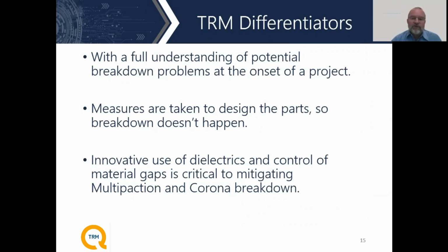We do things like overlapping dielectrics, eliminating gaps, other void filling things that we do to make sure that these sorts of failure modes really just can't exist. It's part of our culture with what we do here to make sure that we don't get into a situation down the road where we have problems with these.